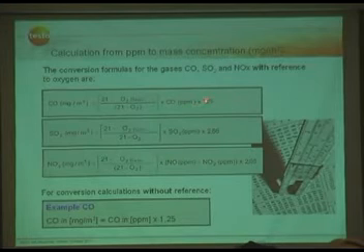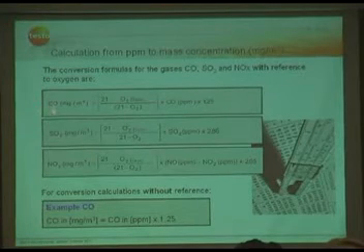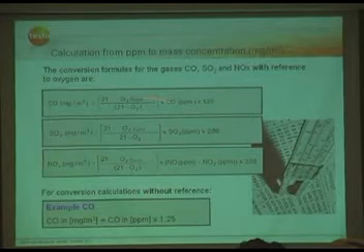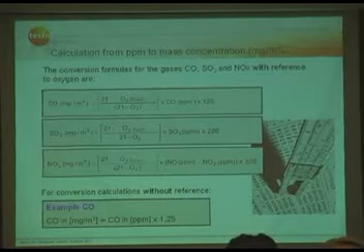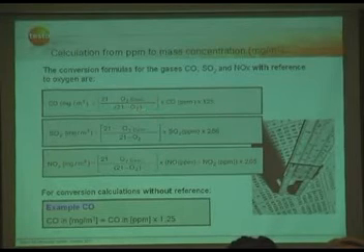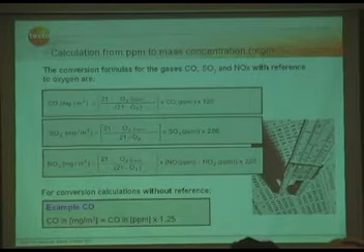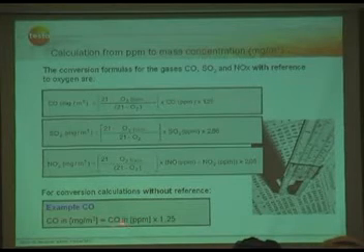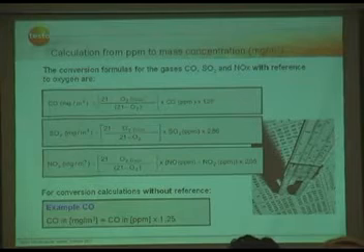And at the end, you multiply with the specific density of the air at norm conditions at 0 degrees C. This is very important, that you refer your readings to norm conditions. And this will take place in the analyzer, because you can show ppm readings or readings in milligram per cubic meter, and the instrument will do this calculation automatically, and you can provide both values. Or in some cases, if you would like to show the readings without reference values, like the O2 dilution, it's just the calculation from ppm times the density of the specific air.